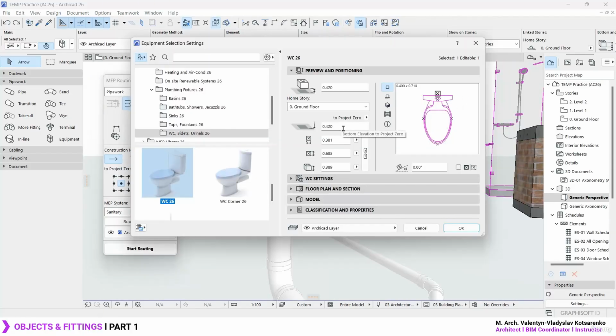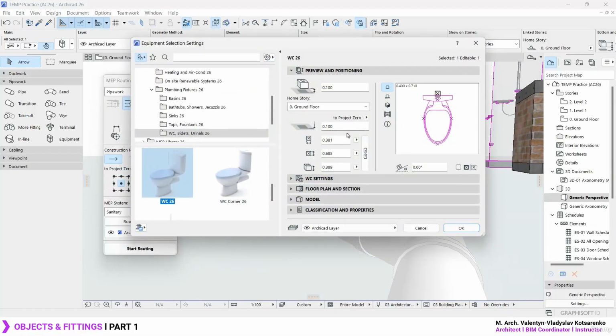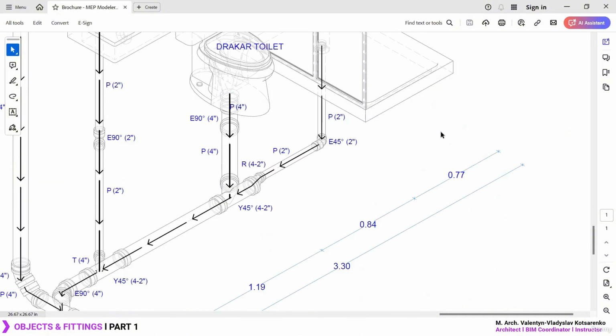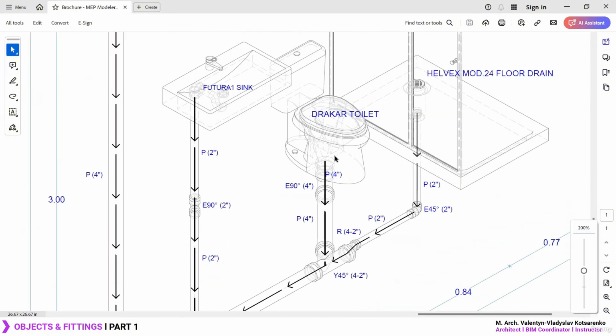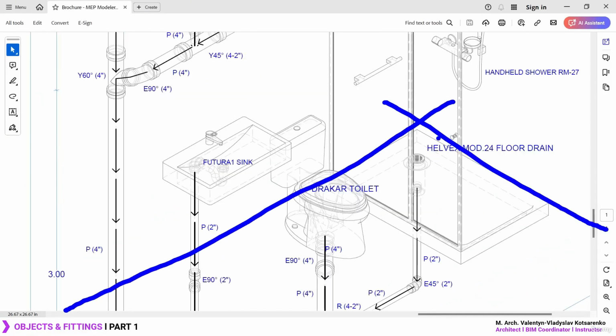Let's go ahead and set the general displacement to be 0.10 just as a general criteria. Okay, I'm just going to keep it maybe 0.20. You can always work this however you want. The main point over here is that you practice this example. I'm just going to set everything to match the same axis as we would have an imaginary wall over here.